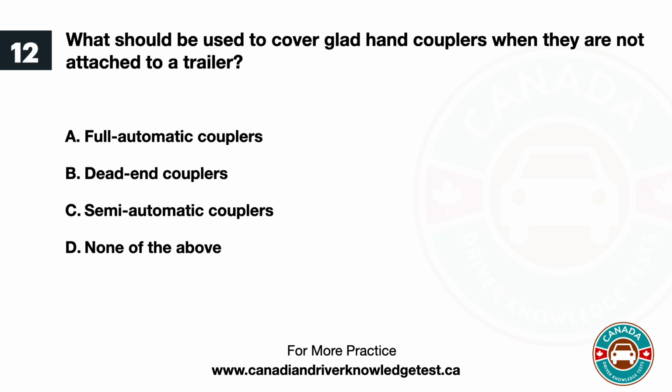Question 12. What should be used to cover glad hand couplers when they are not attached to a trailer? A. Full automatic couplers. B. Dead-end couplers. C. Semi-automatic couplers. D. None of the above. The answer is B. Dead-end couplers.